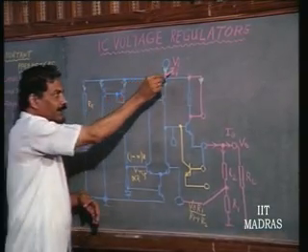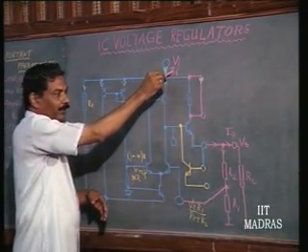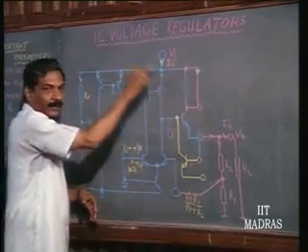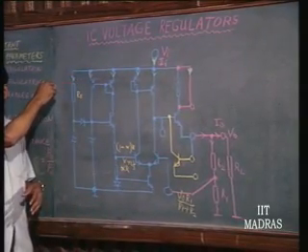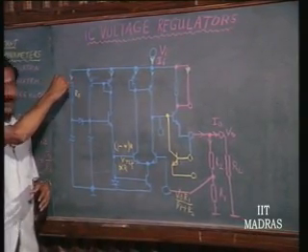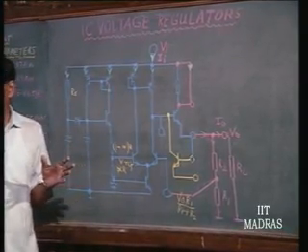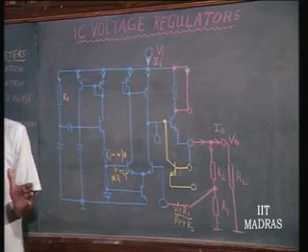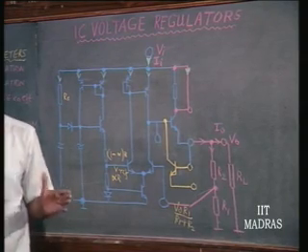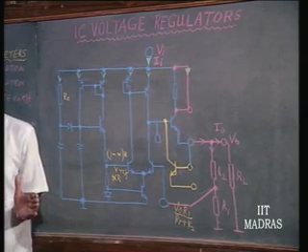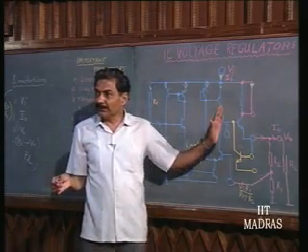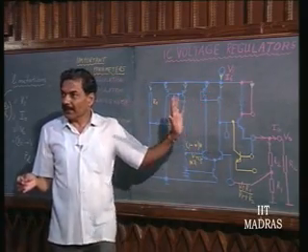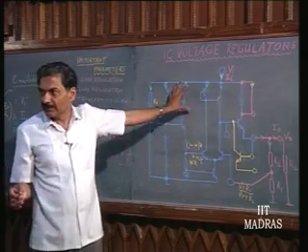So, input current is normally going to be output current plus the various bias current drawn. And in a good, efficient circuit, input current has to be very close to output current, because for biasing these things you should take as low a current as possible. Is that clear?